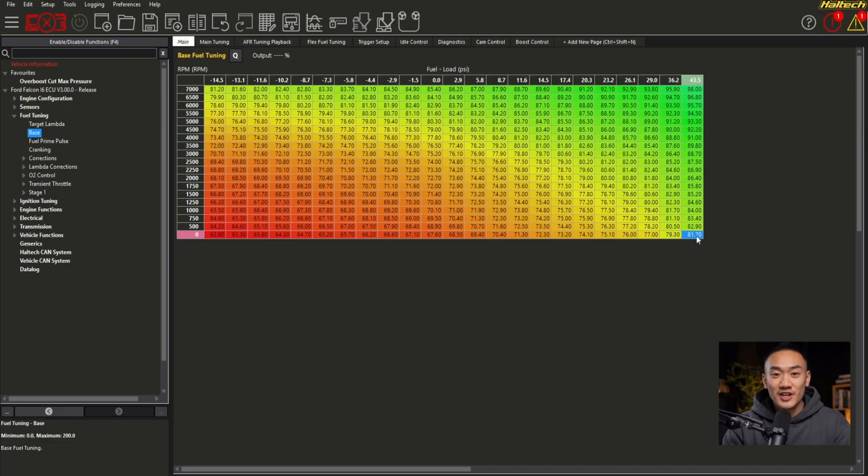Internally, the ECU uses a simplified form of the ideal gas law. You don't need to memorize the equation, but you do need to understand what it's doing. In simple terms, the ECU combines engine displacement, manifold pressure, intake air temperature, and the VE value. The result is grams of air per cylinder. That air mass per cylinder is then scaled by engine speed to calculate total airflow, and from there, fuel mass is calculated using lambda and stoic.